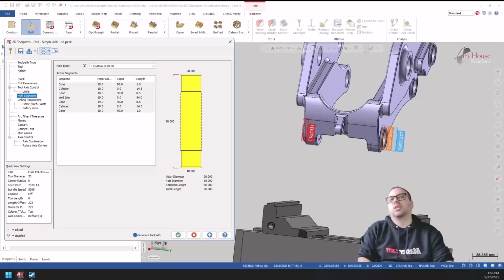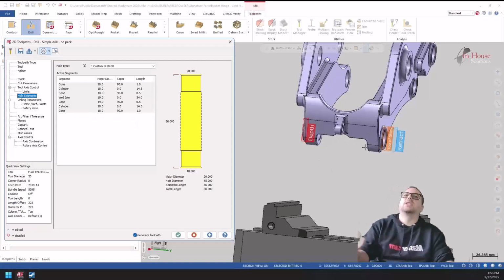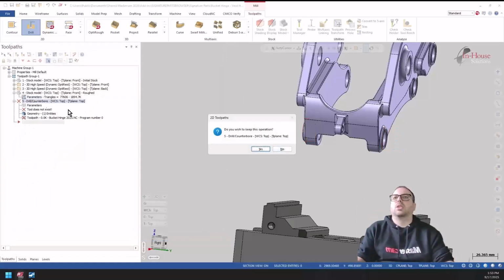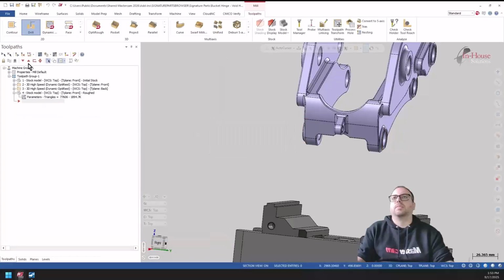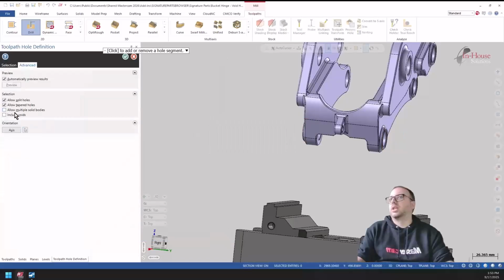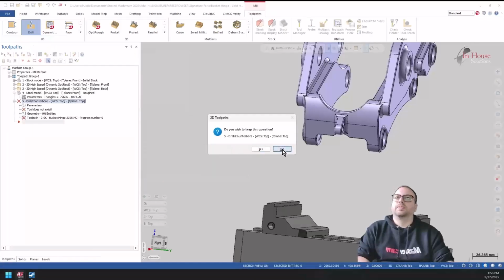Now, obviously, you're not going to be peck drilling all that, but let's say it was not machined yet and it was the first feature you would do, then you can combine those two together by using the void option in the drilling selection, include voids or not. So that's all up to you.